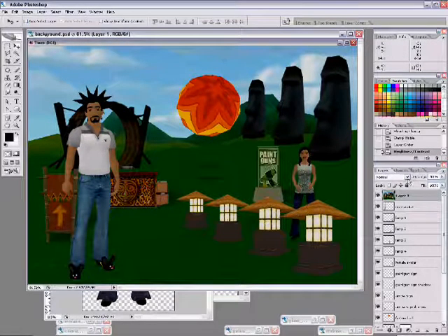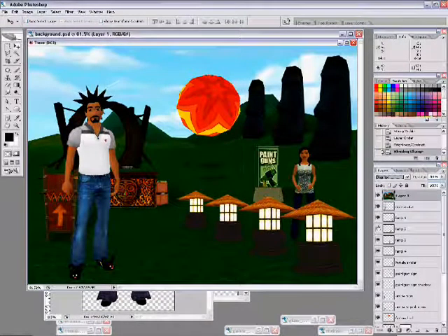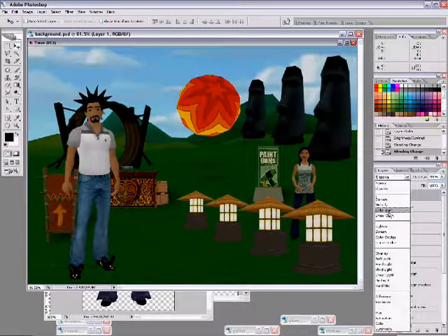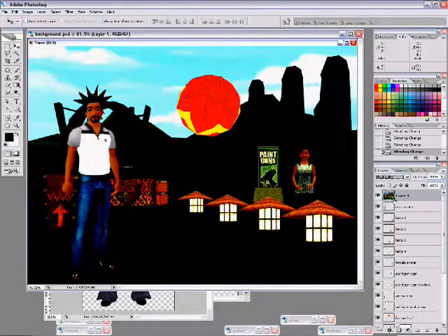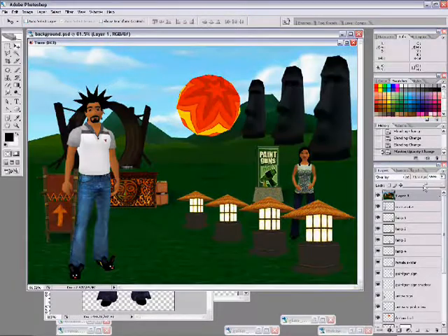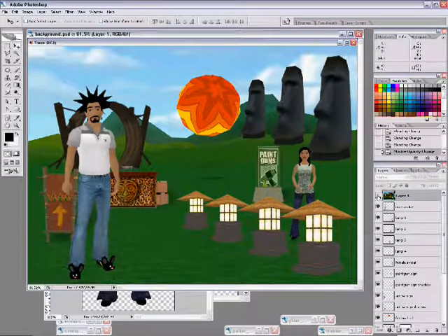And go ahead and change it to an overlay. And what we get is our image differs. We have a little bit more oomph with what we want to do. Okay? But let's do an overlay, and what we're going to do is take the opacity down just a little bit, so we get a little bit more oomph in our image. But that's what Merge Visible is all about. So anyway, we've worked with layers.